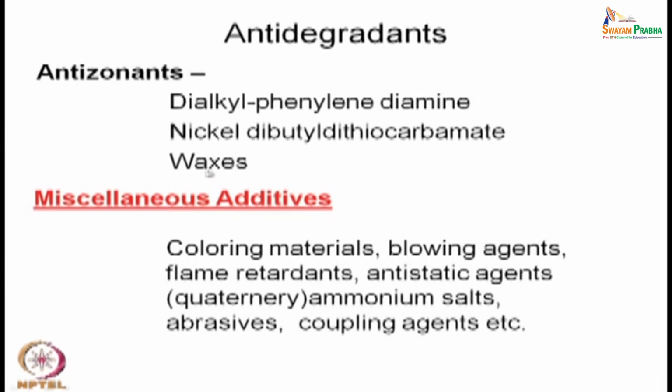That wax is saturated, so that saturated thin coating prevents the ozone entry to the vulcanized rubber surface. So, that prevents degradation by the action of ozone.